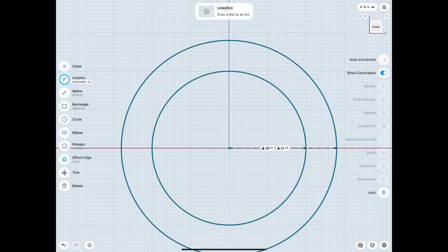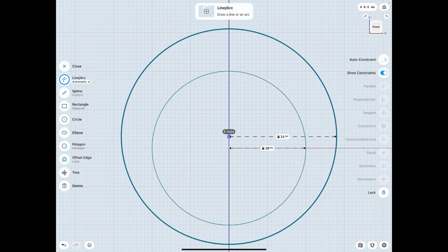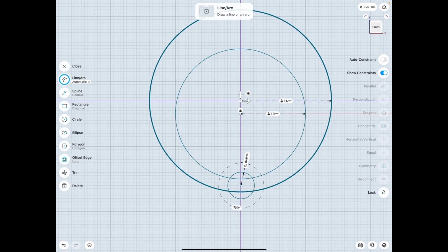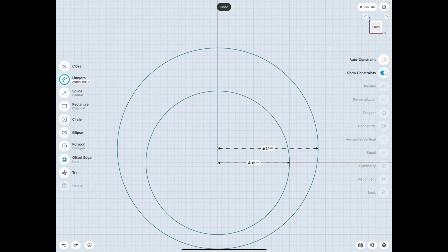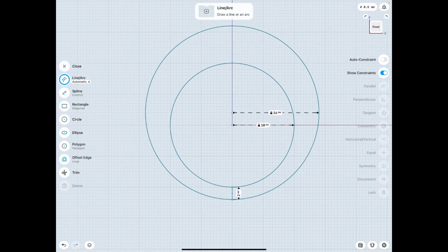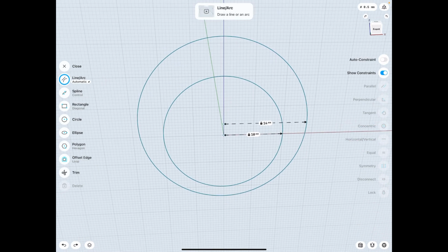If we want it to be exact in the center, no problem, if that's the kind of ring you want. But I want a signet ring, so it's going to be a little bit thinner on the bottom of the shank, right down in this area, and a little bit thicker up top there. Okay, so this, we can just double check. The thickness is 2 millimeters, which I know from experience is a nice thickness there. And now we're ready to go.